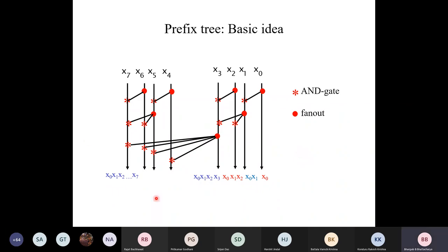So if I design this structure, what do we see here? What is the cost, delay, fan out? I mean, from a hardware perspective, these are the parameters, right? The cost means how many AND gates I am using here. And fan out is important from the hardware point of view, because when the fan out increases, the delay increases, the cost increases, and so on. And the most important thing is the signal delay, because when you want to design this carry look-ahead adder, my primary objective is to reduce the delay, right?